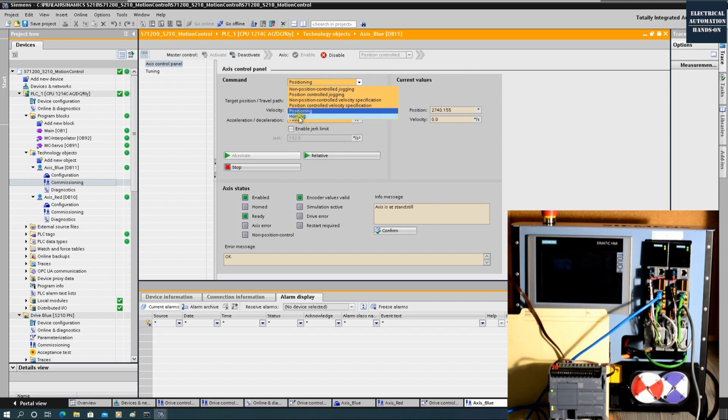For the positioning control, firstly we can go to the homing, and we can home that first. So we can set the current position to 0. Okay, we set to 0. Then we go to the positioning. Without setting the 0, set home, you are not able to move absolute. Okay, you have to go to the homing, set home at first.